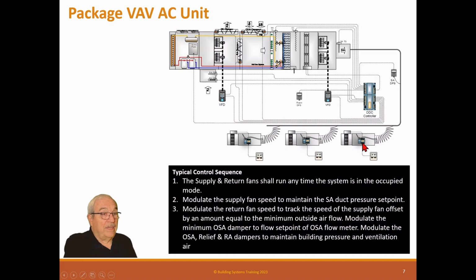at the same time. Now there's such a thing as diversity, which I won't go through, which is in the TAB courses. If you look at the one that's balancing a variable volume system, it explains how these are all set up. For this course, we don't need to know that. So basically these are balanced so that these will always work even if it's a full flow.